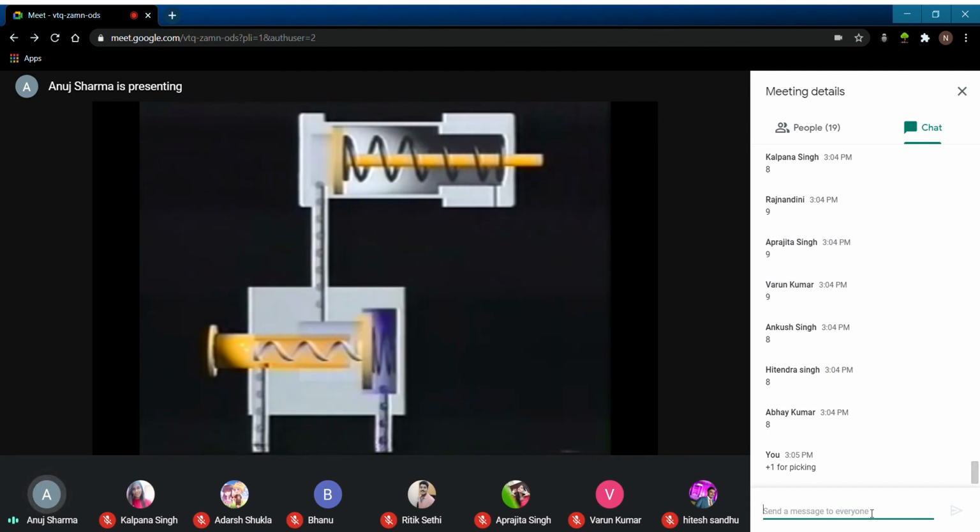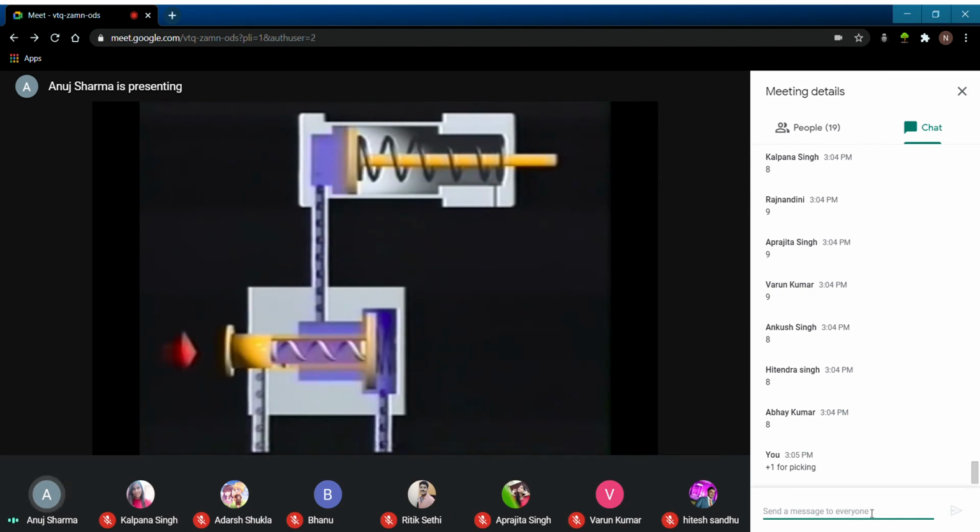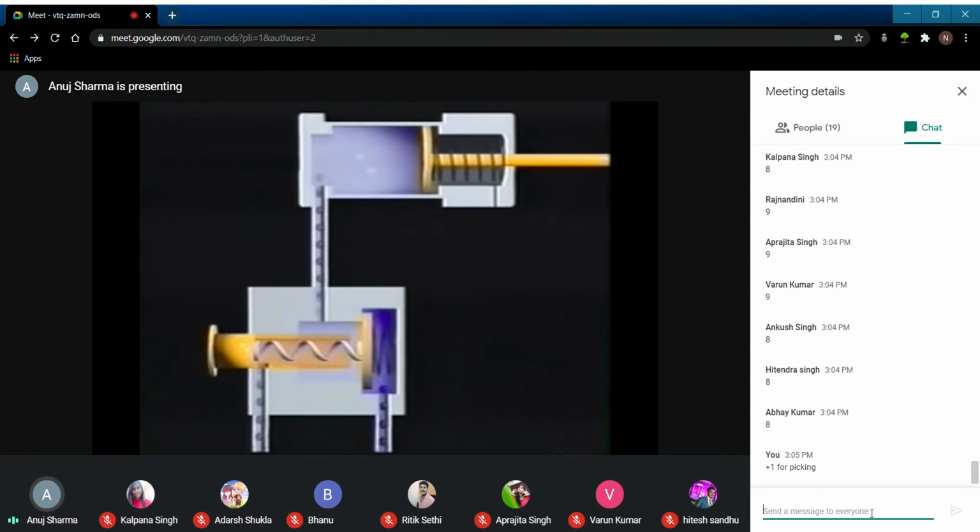This valve is shown with a push-button actuation and spring return. Unactuated, the valve blocks the flow of air to the cylinder, and air exhausts from the piston side, allowing the spring to hold the cylinder retracted. When the button is pressed, the valve shifts, connecting the compressed air port to the cylinder. This causes the cylinder to extend, and the valve blocks the exhaust port. When the push button is released, the spring built into the valve shifts it back to its starting position. The cylinder is then connected to the exhaust port, and the cylinder spring returns the cylinder to its initial position.